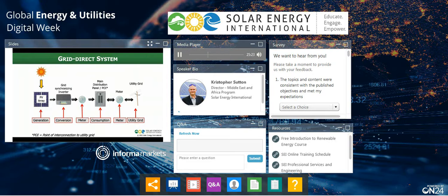And now we have the ability to feed the on-site electrical loads from solar and from the utility grid together. So all of that electricity is synchronized in that main distribution panel and able to feed our electrical loads when the solar is available. Now, where that energy goes is going to be dependent on how much solar output we have. So how many watts or kilowatts or megawatts is the output of the AC side of our solar system, and how big is the solar array, and how sunny is it? Those are all going to change the output.